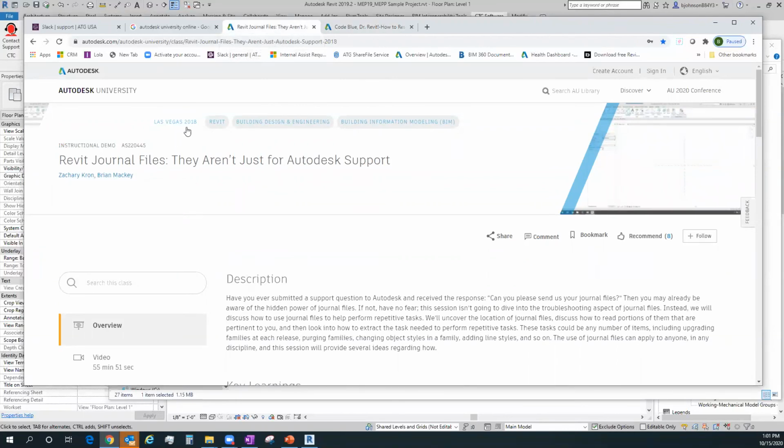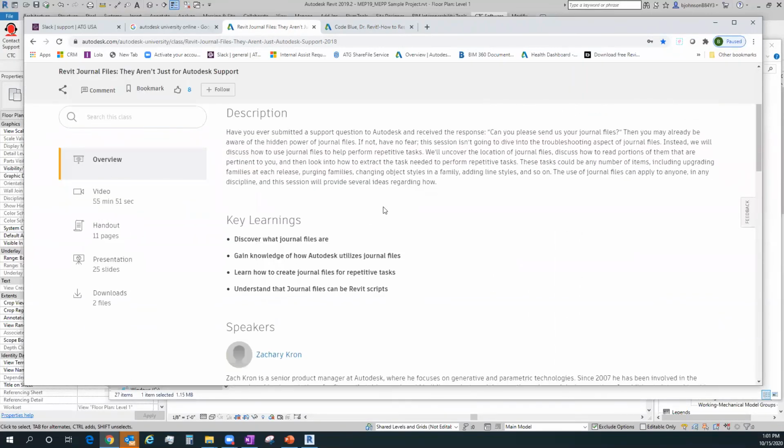I forget what year this was. It was 2018. Revit journal files, they aren't just for Autodesk support. That is a very good session. If you go into the video, the handout, the presentation, slides, and the downloads, they show you what you can do. You can see there's understanding how journal files can be used as Revit scripts, like I just talked about, and how to use a journal file for repetitive tasks. So these are things you can do with a journal file that aren't really for the troubleshooting side, but you can do lots of things with them, especially generating Revit scripts.